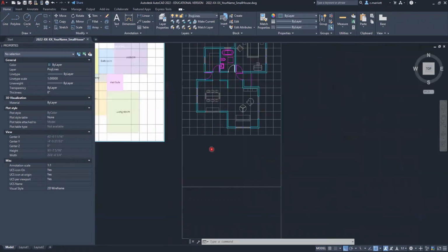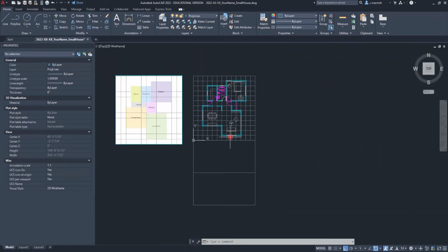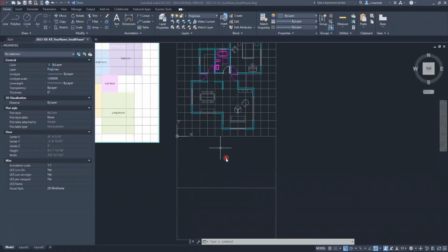All right, we will start with drawing the elevation. So I'm going to begin pulling lines down that will be appearing in the elevation drawing. Now keep in mind the difference between these two types of drawings. An elevation is like you're standing outside of the building looking straight at it. So in other words, your line of sight is perpendicular to the face of the building. A section, on the other hand, is like a cut made through the building and then showing what you see on the inside. Our elevation will be on the lower part here, and our section will be on this upper part.